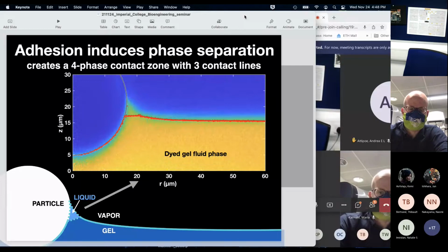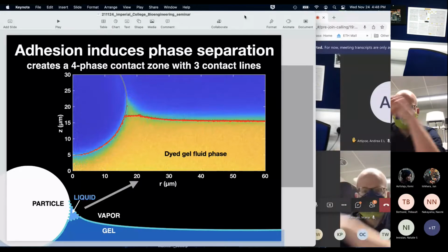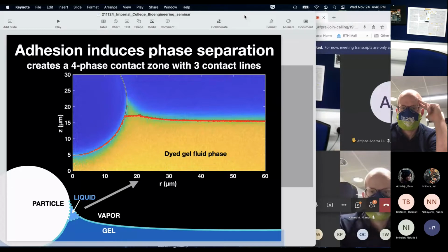But with respect to the liquid, the way we make the gels, we don't extract them. So they always have uncross-linked fluid in them, and that's part of what makes them so soft, because they're not heavily cross-linked. Consequently, there's always some unbound fluid, and the total amount does depend on the amount of cross-linking.